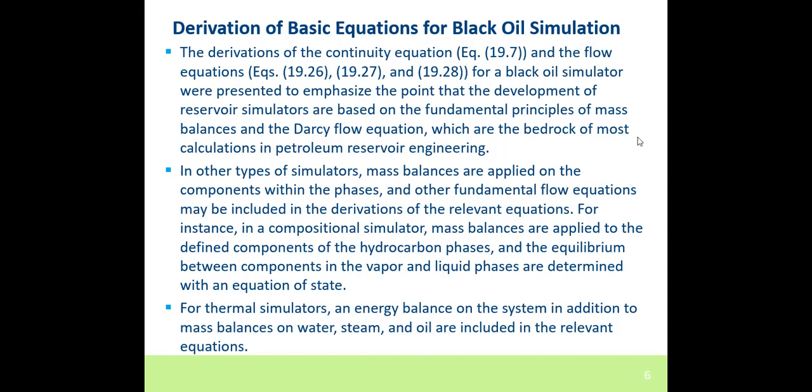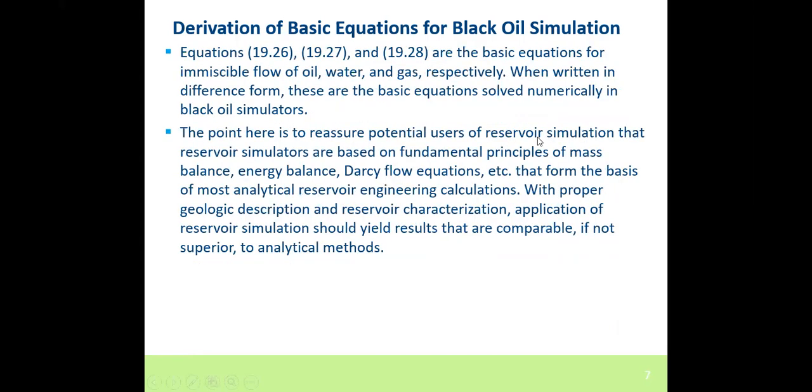Now, Chigozie, follow me on this point. The equations I've shown you before are the basic equations for immiscible flow of oil, water, and gas, respectively. When written in the difference form, these are the basic equations solved numerically in black oil simulators.